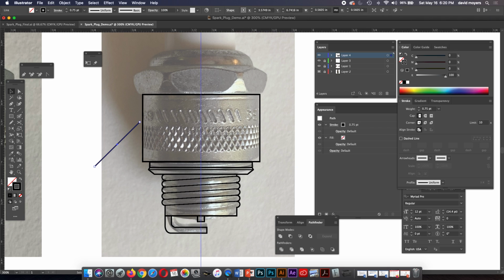Okay, we're going to copy this line, bring it over here like this. Whoops, I meant to copy. So as I'm dragging, hold down my Alt or Option and my Shift key because I want it straight across. Okay. Now I'm going to do a blend. I wanted to show you how to do blends because blends can save time. So I've got my blend tool here, and I'm going to click on this line and this line. See, I got a plus sign there.